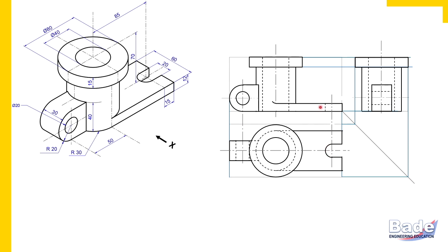Okay, now let's complete this plate in the side view. Which two dimensions do you get in the side view? Width horizontally and height vertically. So let's project the height in the side view. Height of the plate is 12 millimeters. I have projected it in the side view, and width is 20 millimeters, which we have already measured here. Project. Width of the plate, right? Width of the plate is 60 millimeters. So I projected it, and this is how there is a dotted rectangle here.